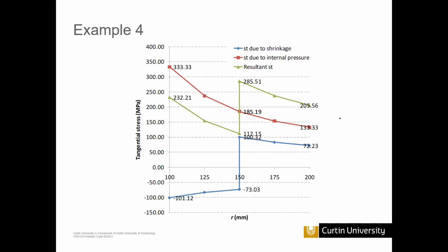So if you use another cylinder, it will be like this. If you use one single cylinder somewhere until here, what happens? It will be like this. So we can't keep the constant pressure buildup towards the radial direction. If you want to keep the constant pressure buildup, we need to use a compound cylinder.